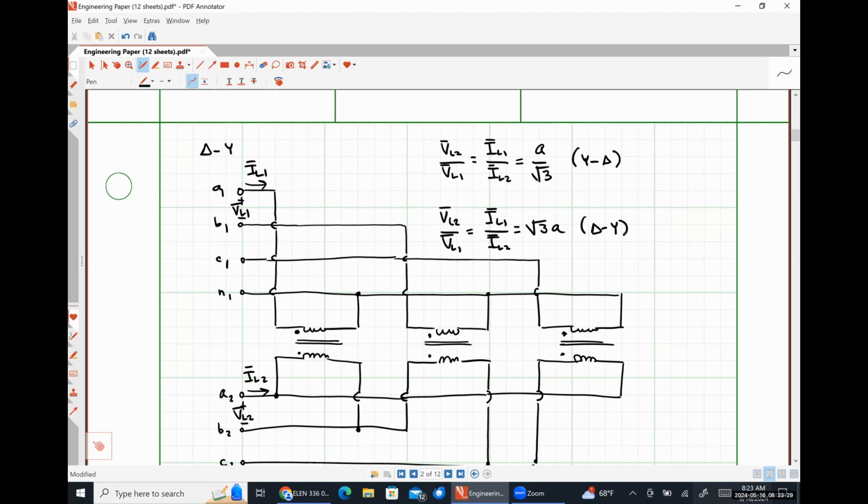Then, if you're going to try to have a grid-tied system, you actually have to make sure that the frequency you have perfectly matches the grid and all of that kind of stuff too. So that's more expensive power electronics that takes care of all of the frequency matching as well. There are multiple degrees of isolation in which transformers are used, by the way, to provide that electrical isolation to make things work.